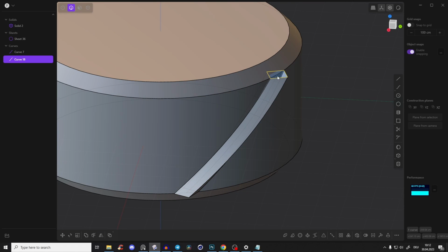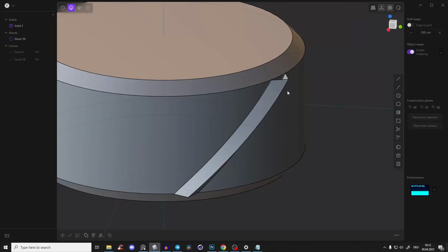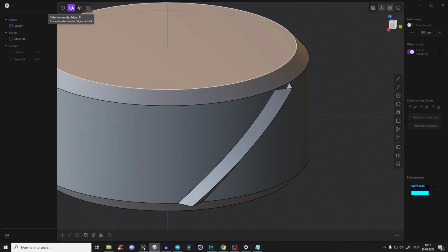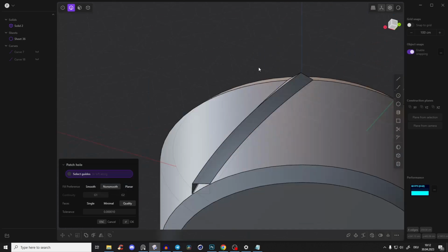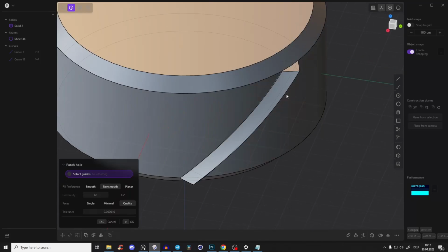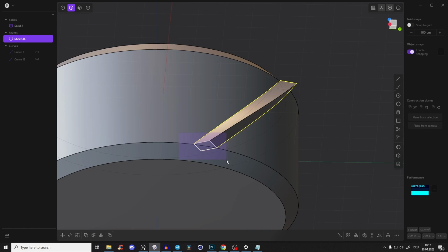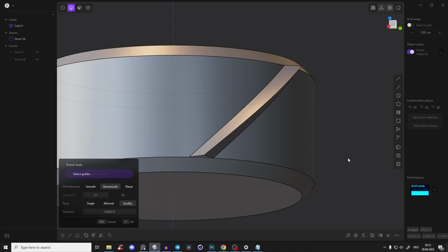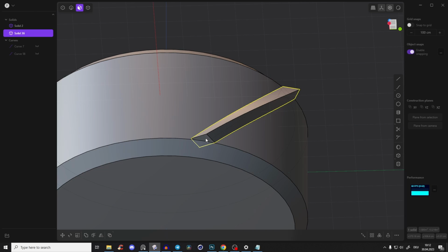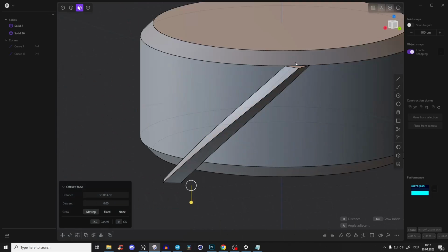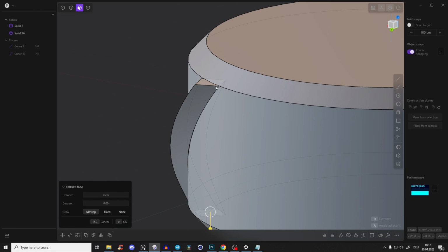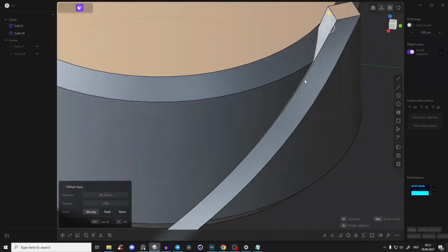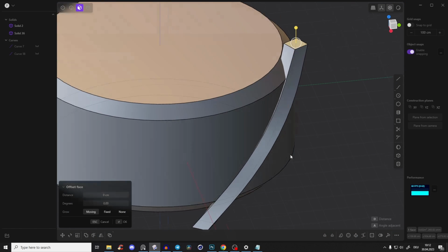Right click and now I will select those 2 curves, press H, I don't need them. And in edge mode, select those edges here and patch holes along edges. I found that will work much faster later when we boolean it. So right click and the same here on the bottom, select those 4 edges, patch holes, right click and now press 3 to face mode, select this face and just extend it, because you see it's now just ending in the inside, but we will cut this main body, so we have to extend it. And we are still preserving this curvature, so this is really fine.